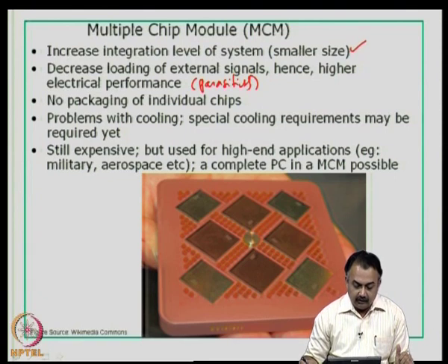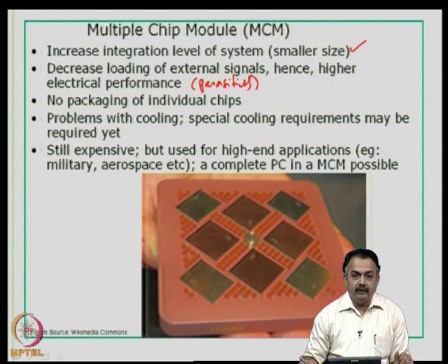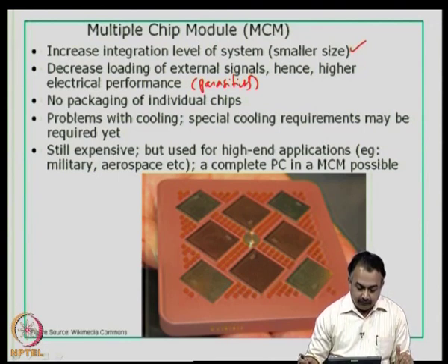Therefore, this multi-chip module, if it is well designed with the physical properties of the substrate taken into account, whether it is an organic or a ceramic substrate, and then you increase the number of layers to handle these signals and power delivery, then we are going to get a highly efficient high performance multi-chip module.